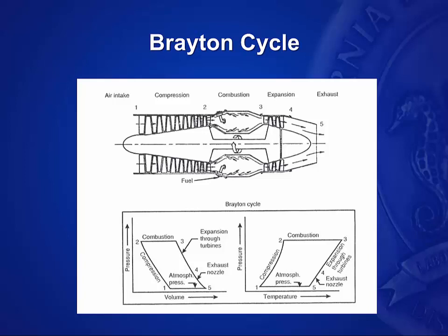The advantage to that is a lot of the emissions do occur during the really high temperature, high pressure that you see in an internal combustion engine. At this lower pressure and lower temperature that the Brayton cycle occurs at, you have fewer pollutants such as NOx being produced. But anyway, let's look at the Brayton cycle itself.